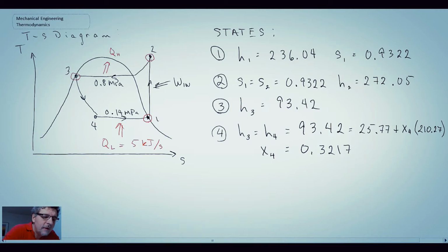So there we have all of our states, we have all the information. This is actually the answer to the first part. We can now go ahead and use the values of enthalpy, applying the first law for each of the different components, and determine everything that we need to determine.